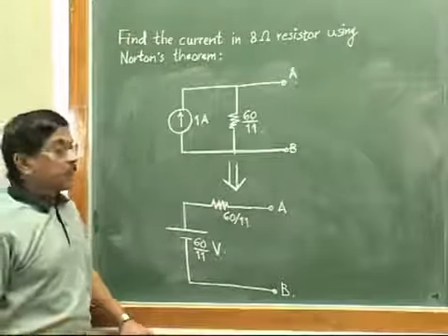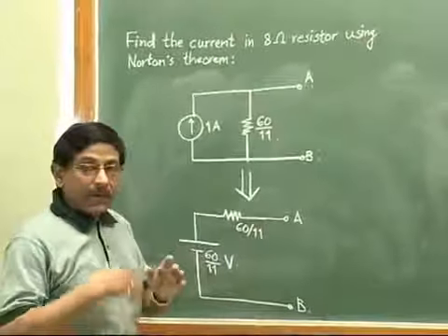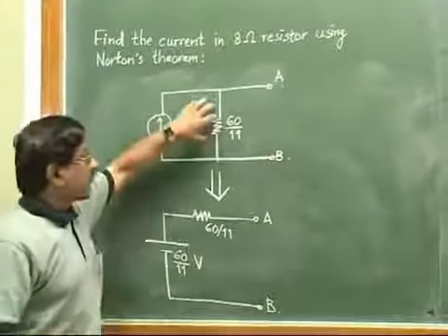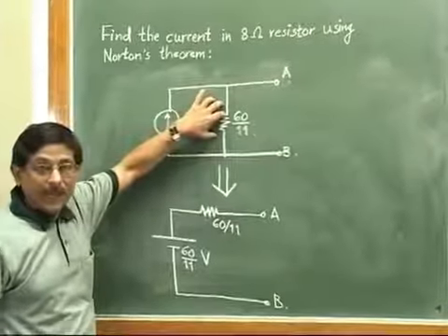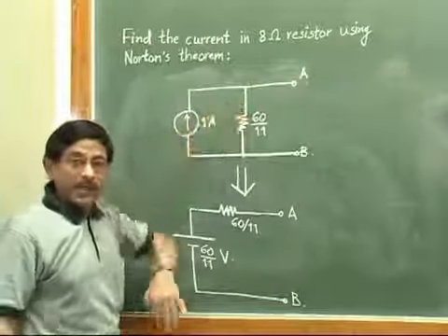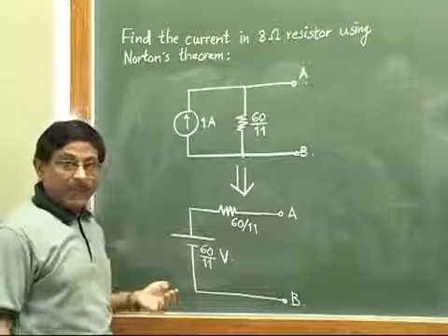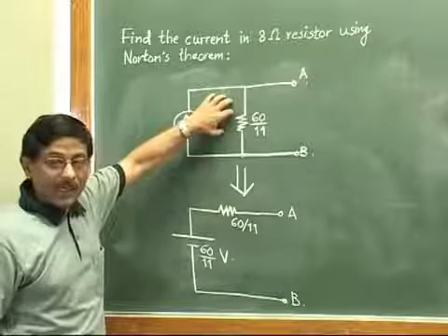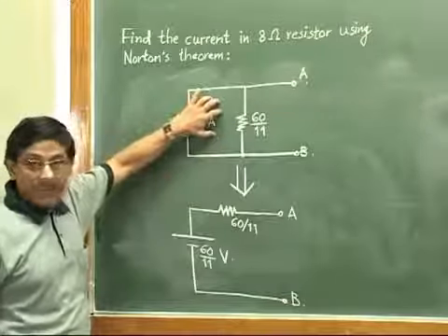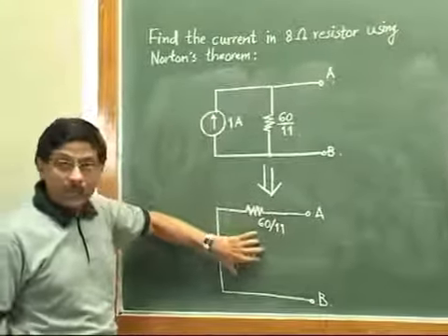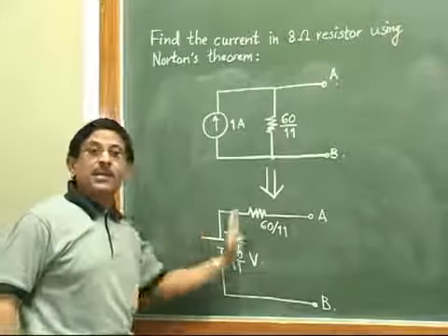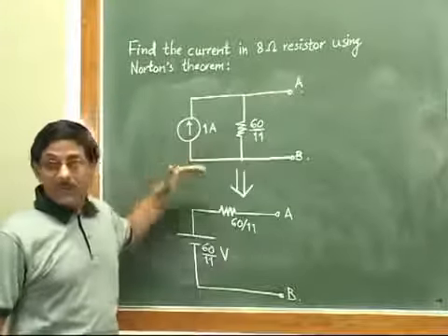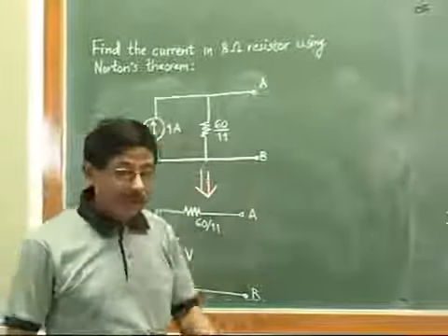That means if you solve any such problem with one of the theorems, either Thevenin's or Norton's theorem, and if you convert the equivalent circuit you finally get into the other type of source, suppose you solve the problem with Norton's and you get some circuit like this, and you convert this circuit into an equivalent practical voltage source, you will get exactly the Thevenin's equivalent circuit. That's why it is said that Thevenin's and Norton's theorems are complementary to each other.